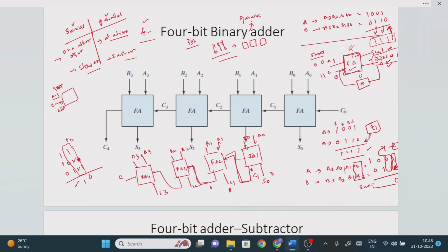So like this we need to find the output by using the 4-bit parallel adder, right? See, here there's a diagram. Initially we don't require the carry, because by default you can consider a half adder also. This is correct because by default the initial bit doesn't have any carry, so carry equals 0, and if you consider a half adder it will also work. For the remaining stages we need to consider full adders only. If you have confusion, just consider this also a full adder. This is not mandatory for the first full adder, because by default no carry is generated in the LSB operation, right?